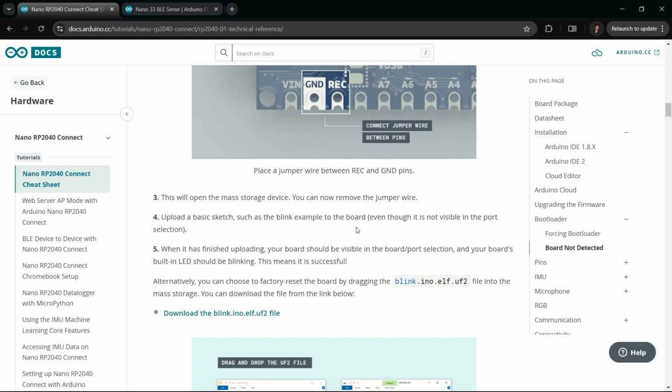But another advantage that RP2040 gives is for you to be able to write the code externally, outside of the device, just like Arduino, and then drag and drop the code file into the board. There are different ways of doing this. If you're using the Thonny IDE, or OpenMV camera form of programming, or the direct conversion from Python code, if you're programming with MicroPython, you can just drag and drop from your computer onto the device. It's going to automatically read it as the main file.